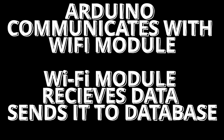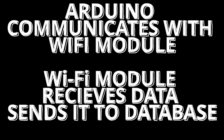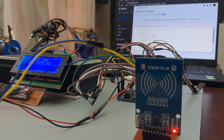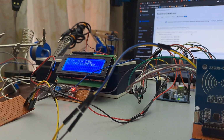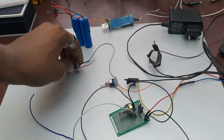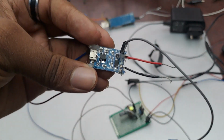That's how it's programmed. Now, as I said before, this project should be able to run whether there is power supply from the AC mains or not, and that means that it's going to have a rechargeable battery system. Now, let's keep it quick and short. Each of the batteries has their own charging module. Those charging modules are each supplied 5 volts from the same supply.